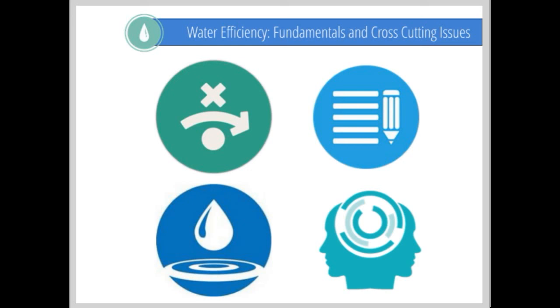A project that includes gray water reuse, rainwater harvesting, municipally supplied wastewater, purple pipe water, or other reused sources is eligible to earn credit in WE Credit Outdoor Water Use Reduction, WE Credit Indoor Water Use Reduction, WE Credit Cooling Tower Water Use, and WE Credit Water Metering. But the team cannot apply the same water to multiple credits unless the water source has sufficient water volume to cover the demand of all the uses. For example, irrigation plus toilet flushing demand.